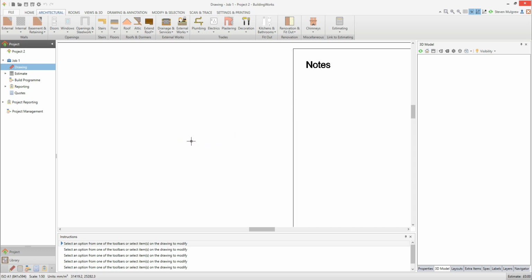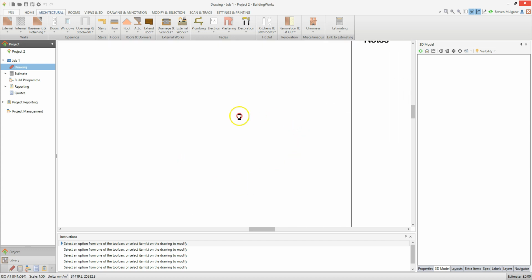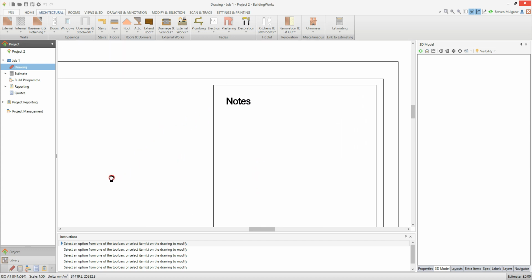Press and hold down the scroll wheel or middle click button if you have one. A hand icon appears on screen. Keeping the scroll wheel or middle mouse button held down, move the mouse to move the page around the drawing area. The skills of zooming in and moving around the drawing page are important ones to master. Spend a few moments practicing with your mouse until you feel confident moving the page around and locating and zooming in on points of interest on the drawing.